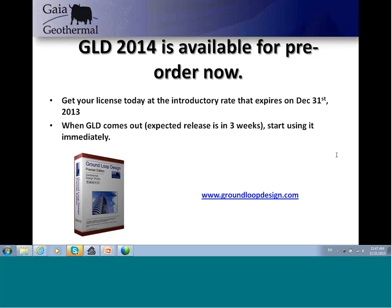So, several good questions. Any other questions about anything? Another question: what is your typical target max entering water temperature? A fluid cooler doesn't really work until there's a delta T with a loop temperature higher than ambient, so 85 is an unreasonably low target, but perhaps 95.